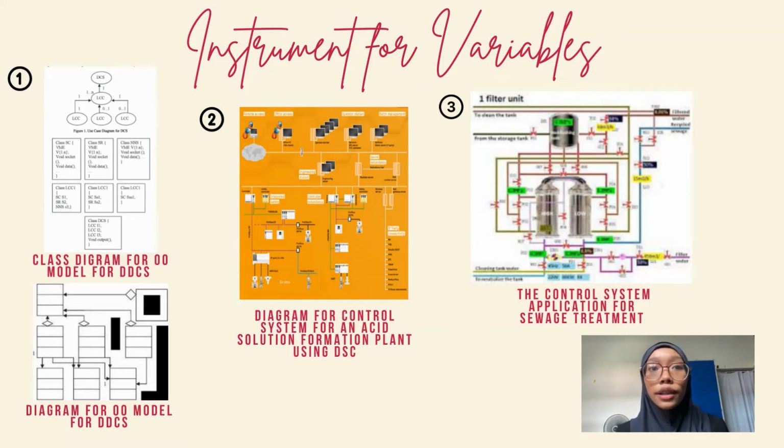And the last one is OLE for process control (OPC) and DCS to connect simulation system, as well as in order to get data shared by various industries. By this, for the training of engineers, DCS commissioning or maintenance, verification test of the control strategy, the connected system can be utilized to avoid exploding equipment, for improving improper parameters, and decrease the cost of commissioning.